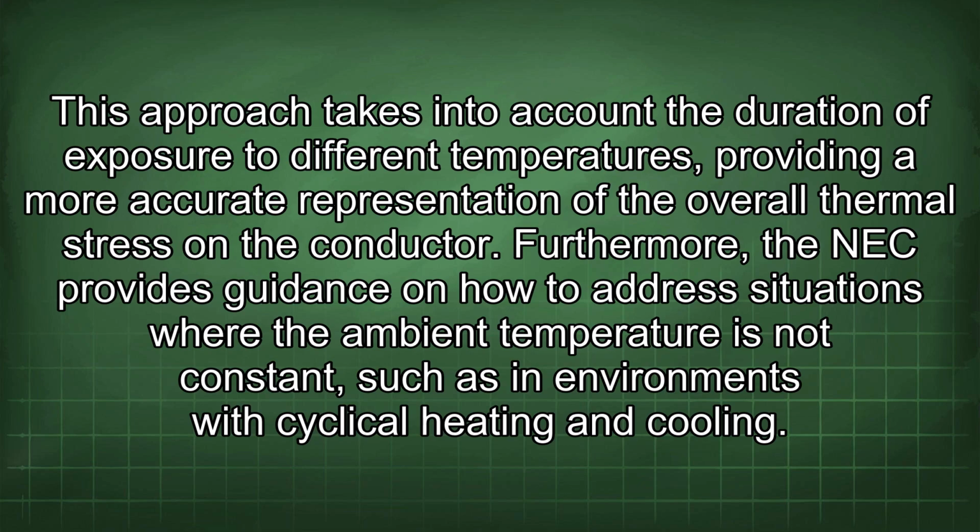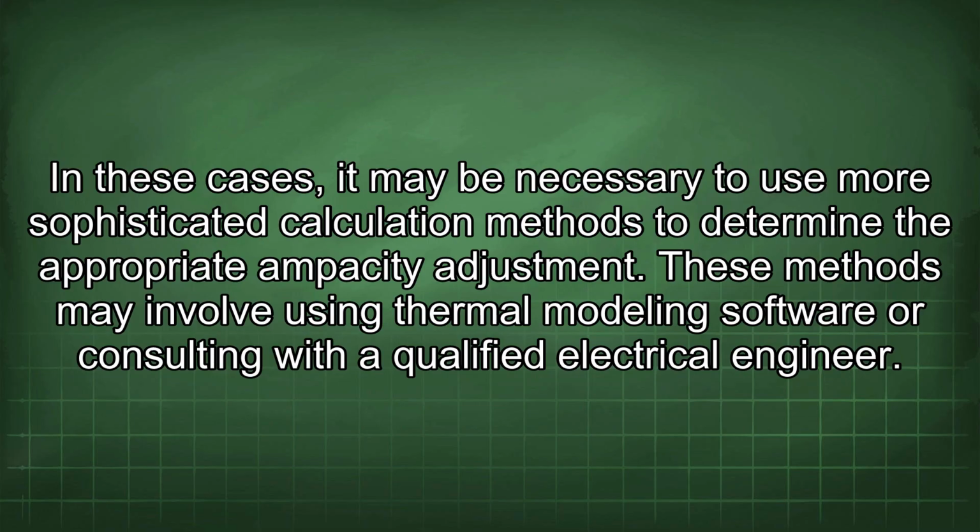Furthermore, the NEC provides guidance on how to address situations where the ambient temperature is not constant, such as in environments with cyclical heating and cooling. In these cases, it may be necessary to use more sophisticated calculation methods to determine the appropriate ampacity adjustment. These methods may involve using thermal modeling software or consulting with a qualified electrical engineer.